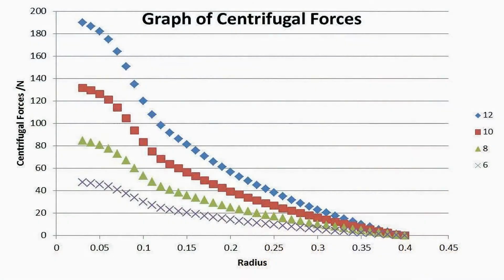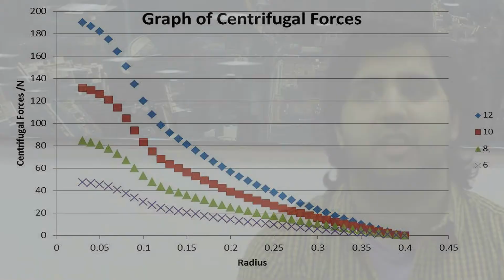Following this, the equations for circular motion were used to find the centrifugal forces and subsequently the stresses for each of the blade elements. From our calculations, we saw that the stress values on the blade were lower than the peak tensile failure stress of ABS plastic, therefore it was structurally sound.